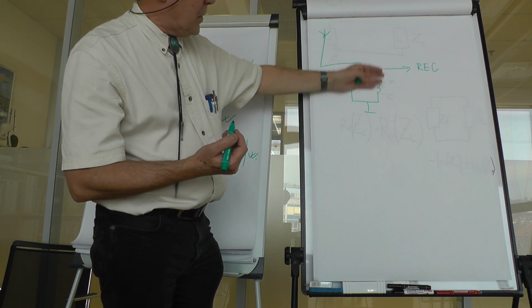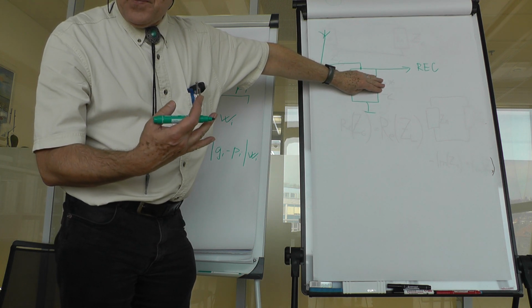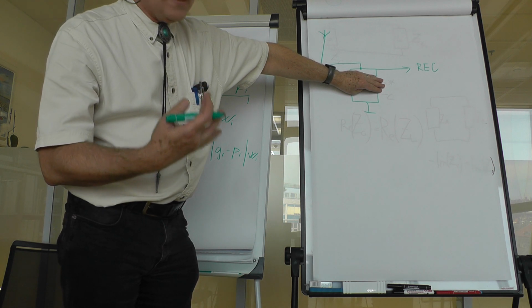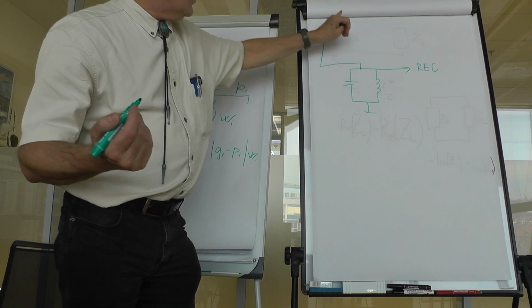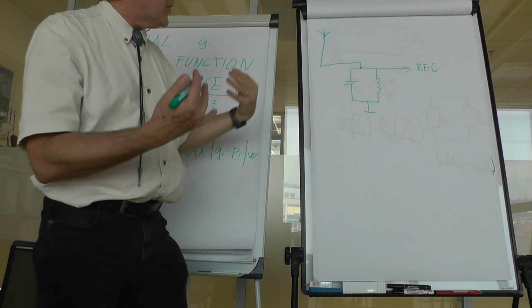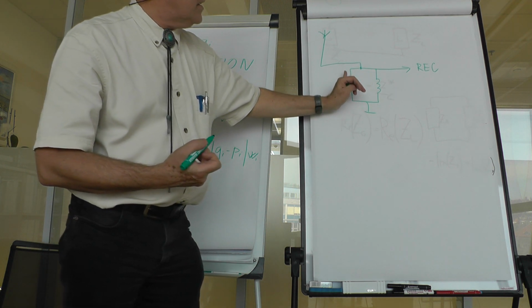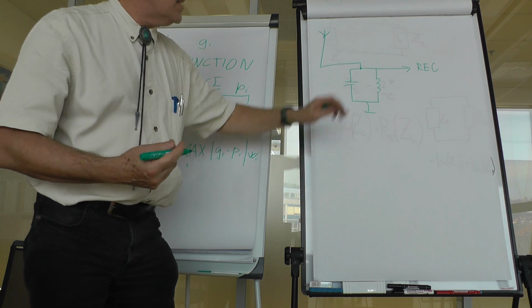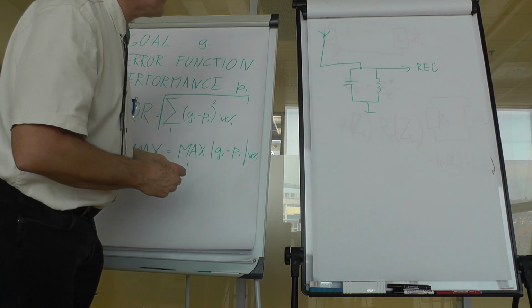So in fact, a parallel resonance circuit is not in the circuit. The impedance of a good parallel resonance circuit in resonance is reaching infinity. So all the signal goes to the receiver. At other frequencies, at lower frequencies, the signal is shunted by the inductor. At higher frequencies, the signal is shunted by the capacitor. So it damps all other frequencies significantly.